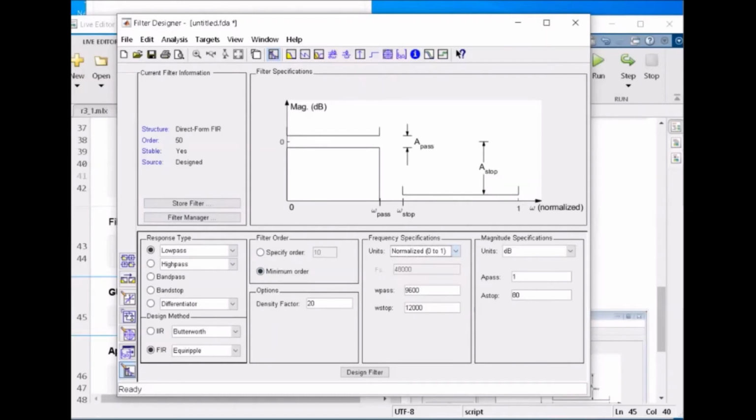You can use here absolute values of your parameters in hertz, or you can use relative normalized values, meaning that one is the Nyquist frequency. I believe that you know what Nyquist is, it's half of the sampling frequency. The name of the half is called the Nyquist frequency.